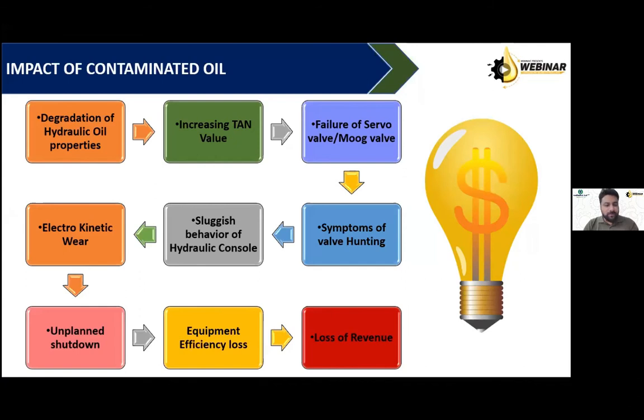So even in the hydraulic systems, the degradation of the hydraulic oil can lead to formation of acids. The hydraulic oil might be the naturally found mineral based oil, or it can be a synthetically processed hydraulic fluid. For example, it can be a water glycol fluid, or it can be a phosphate ester or EH fluid. So many names to the synthetic type of hydraulic fluids.